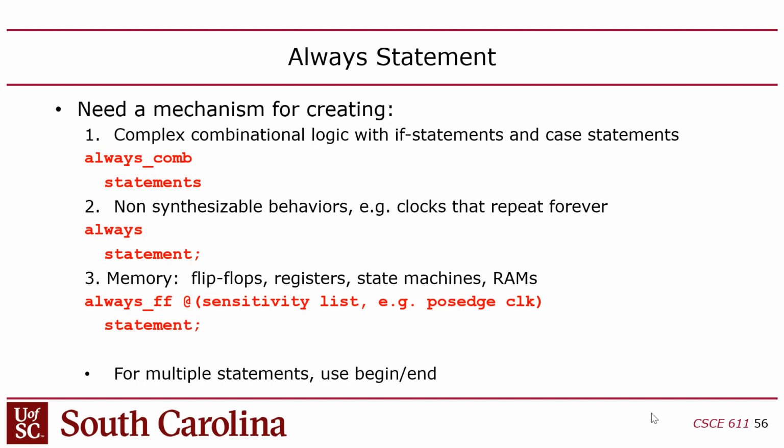in which case you would put always at star. So always at star is going to have the always activated on any signal that's treated like an input in there, which means anything that's used in an expression, right?